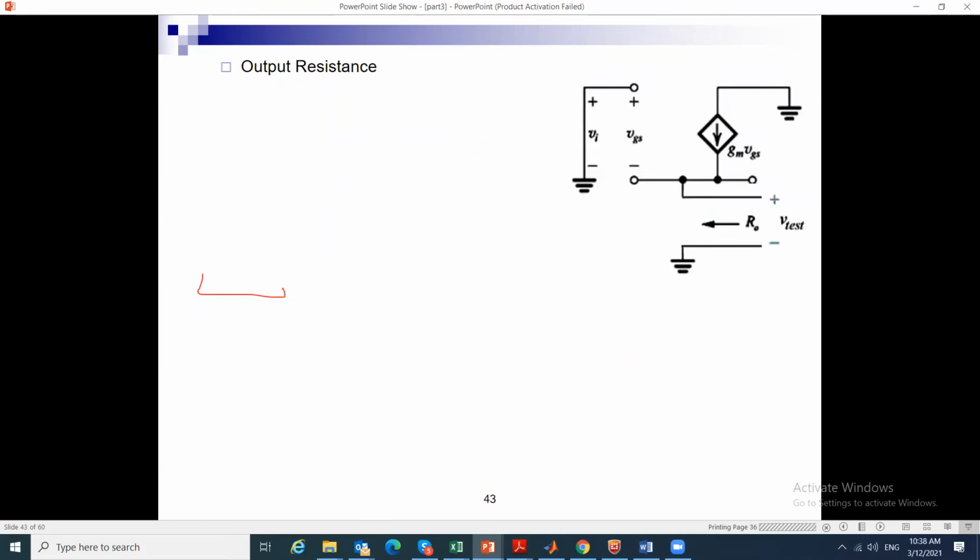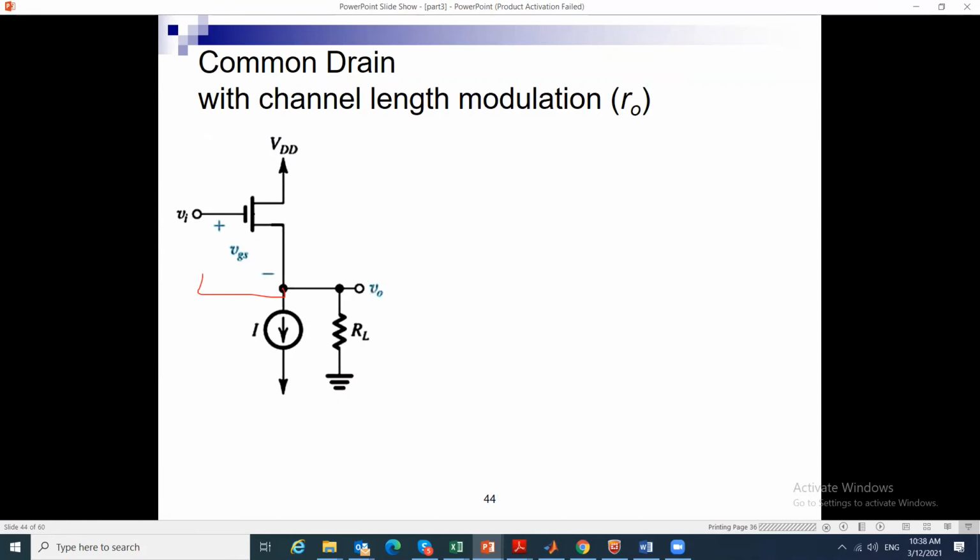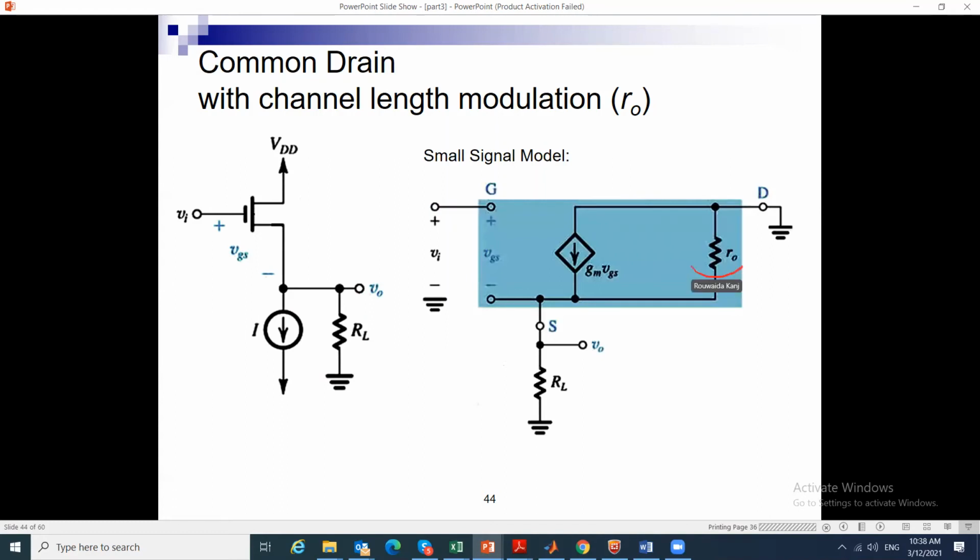The output resistance here is just telling me how it is derived. We don't have to go through this. Now he's saying I have RO, and in the presence of RO, I want to rederive things. So I'm going to rederive the gain, and the gain will involve RL parallel to RO. What happens? Between this node and the drain I have RO, and the drain is grounded, between source and drain. What happens to this RO? It will fall back in here, right? I can remove it from here, and since the drain is grounded, draw an RO at this node.